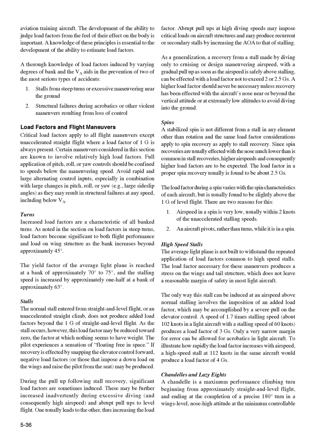High-speed stalls. The average light plane is not built to withstand the repeated application of load factors common to high-speed stalls. The load factor necessary for these maneuvers produces a stress on the wings and tail structure, which does not leave a reasonable margin of safety in most light aircraft. The only way this stall can be induced at an airspeed above normal stalling involves the imposition of an added load factor, which may be accomplished by a severe pull on the elevator control.